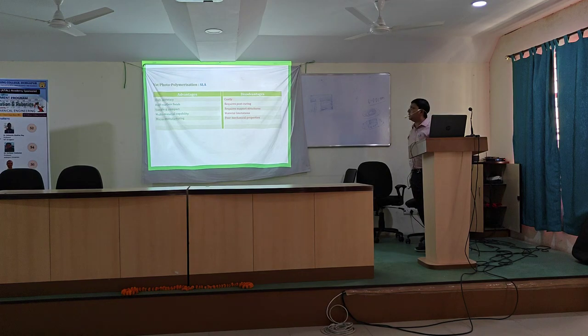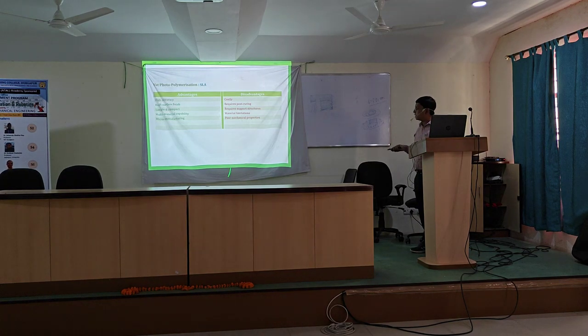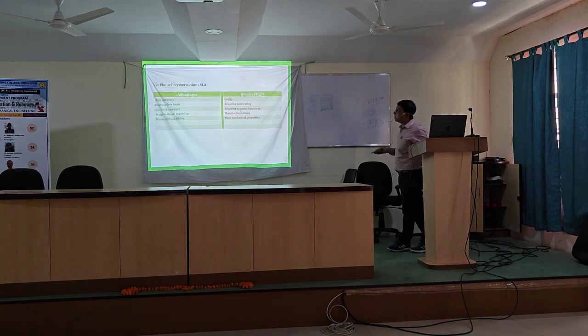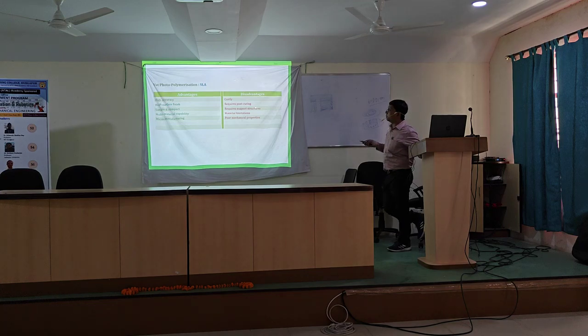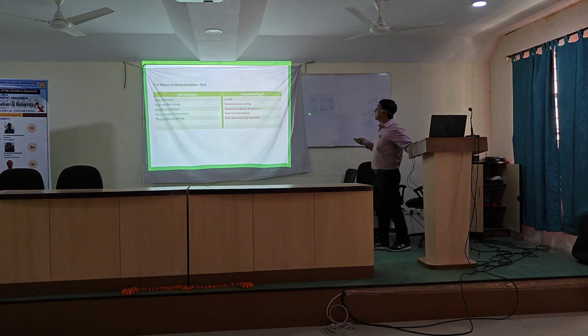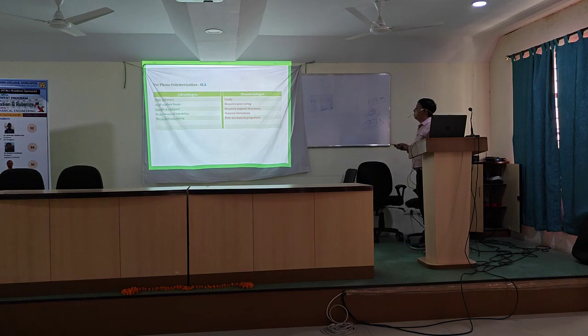And what is the advantage? Advantage is highly accurate product can be manufactured. Surface finish also high. Simple and compact, multi-material capability there, micro manufacturing is possible. But disadvantage is machine is proprietary machine, so machine cost is high, material cost is also high, there is material limitation and support material is required for the overhead portion, so that is why the wastage of material is more. Poor mechanical property because it is made of only the resin material.